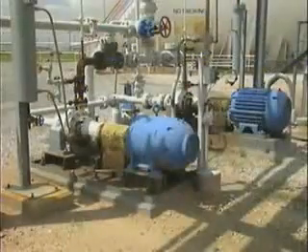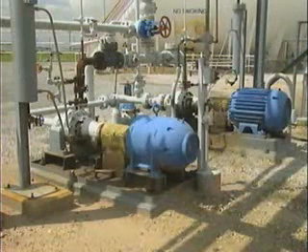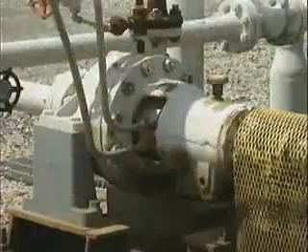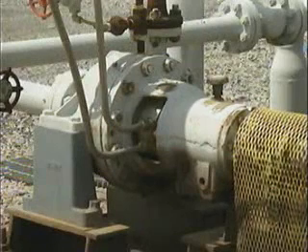In equipment that's operated in low temperatures, a circulating oil's pour point must be low enough to allow the oil to flow freely. Also, the viscosity index of a circulating oil is very important if the system in which the oil is used experiences large changes in temperature.